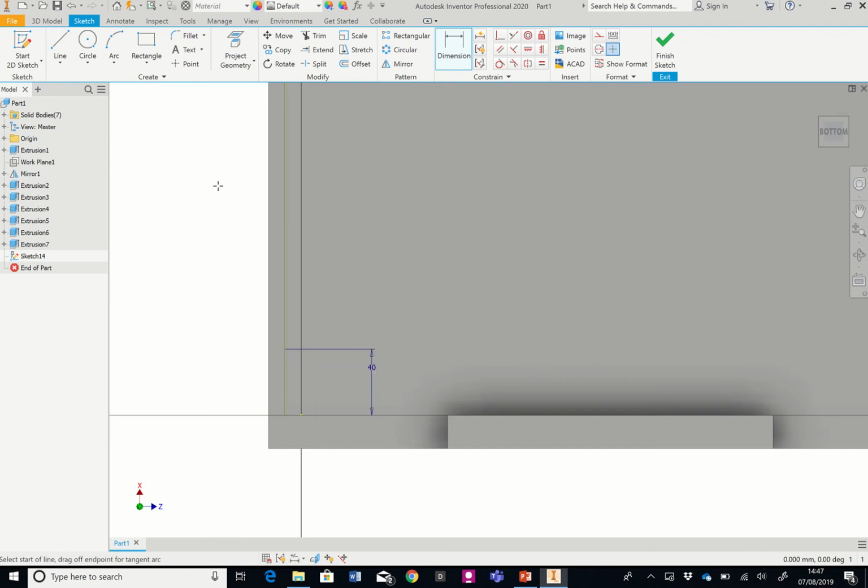And we're going to create a line. This line is going to be at 80 degrees, and we only want it to be 20 in length. So we're going to press 20, press tab, and press 80 for the degrees. Press escape, and then you've got the edge of the line there. That's just a construction line. We are now going to left click on that green dot, make sure that it's 80 in length, press tab, make sure it's 80 degrees, press enter.